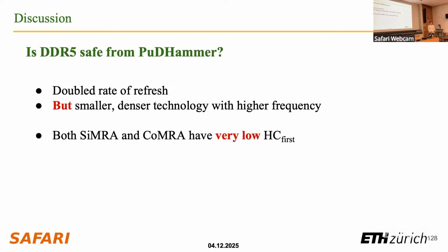But I believe if you're moving forward to enable these processing using DRAM operations, you would need to specify this in the timings, right? So what we do here is activate, violate timing, precharge, violate timing, activate. Instead of doing that, you need to have a SiMRA command that internally does that.